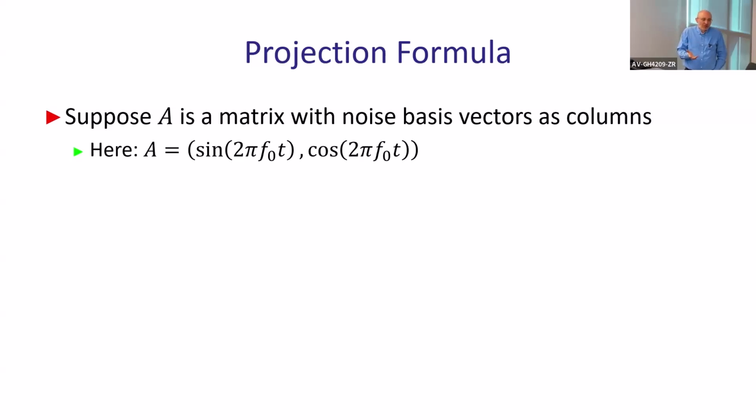If you care about spectral content, which means how much of the 20 hertz I have in my signal, or how much alpha band, like brain waves, from 8 to 13 hertz, how strong is my alpha frequency band in my brain signal? That helps you see if you're semi-dreaming or closing your eyes, which significantly increases your alpha range. In that case, you want a Fourier transform, or something similar,